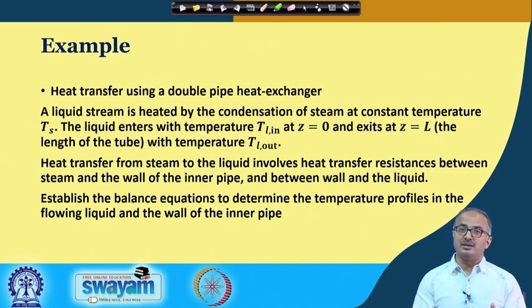Okay? So, in this way we have two types of heat exchange. One is the indirect cooling, that is the first example I gave you, and the second one is the direct cooling, the second example I gave you. So, these are two configurations. Then in the industries you will find that only one contact may not be sufficient. You need to have sufficient contact to cool down or heat up a particular process fluid. So, in that case you need some more contact time, or sometimes you need to give more space to get this kind of cooling or heating.